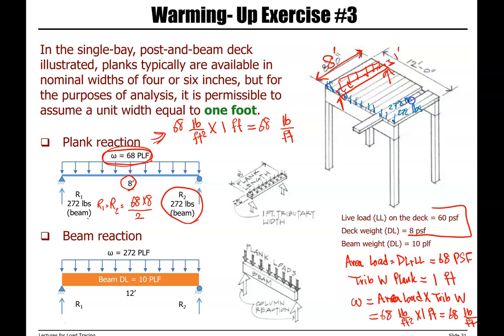Again, each individual plank does that. And the spacing between planks is 1 foot. So on the beam, the load that we have on the beam is 272 pounds.